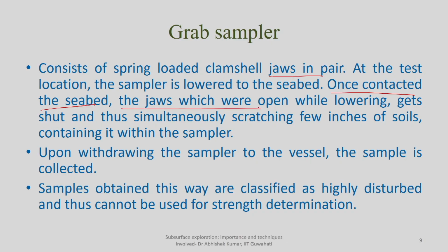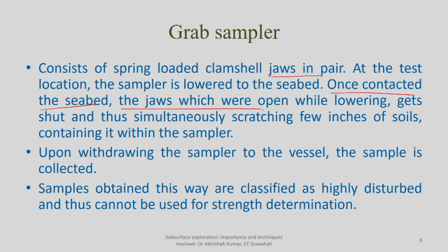So the jaws which were open like this, this is the condition at the bottom of the sampler. When you are lowering the sampler from the vessel, as soon as it comes in contact with the seabed, the spring will release the clamshell, and once the jaws come in contact with each other, they get locked.